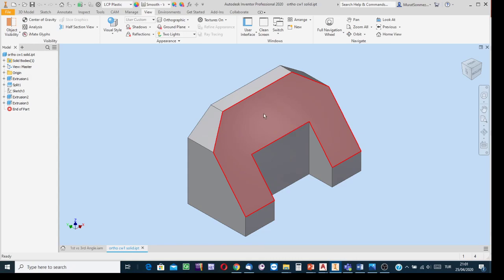Okay, in my method, after selecting the surface to create its model via cutting the material, first see which principal side, which principal picture plane, that surface is perpendicular to. This is perpendicular to the left side surface, also the right side surface. So in my method, after answering that question and saying that it is perpendicular to the left side surface, then over the left side surface, draw the necessary sketch for having the region to apply the cutting process.